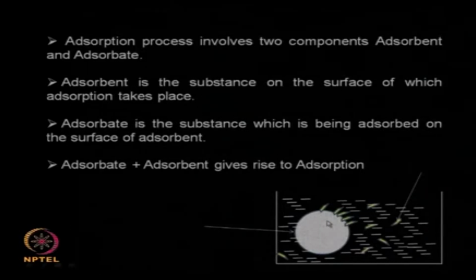The adsorbent is the activated carbon or zeolite or alumina or any solid material, and the adsorbate is a gas or a liquid, small molecule or even large molecules like protein, they get adsorbed on the surface. So the remaining bulk will never have this particular adsorbate present, and generally they form a monomolecular or bimolecular or multilayer of this particular adsorbate on top of the adsorbent.